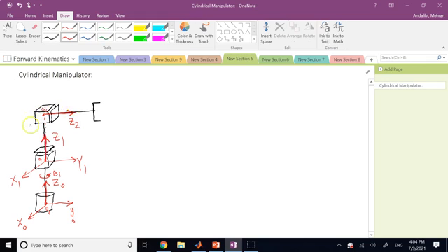And so I have to now draw X2 such that it is perpendicular to Z1 and normal to it. And again, I can select it to be only this direction. Why? Because if I do it like this, then it is not going to be intersecting Z1. It is going to be what? It's going to be parallel to Z1. So here I have no solution other than saying this guy is my X2. Okay, and now with that being X2 and that being Z2, the direction of Y2 is going to be downward, because again, if you remember, each frame has to be basically right-handed. So there we go. I got my Z1, I got my Z2, Y2, and X2. Good. So everything is set. So the first 3 frames are set.